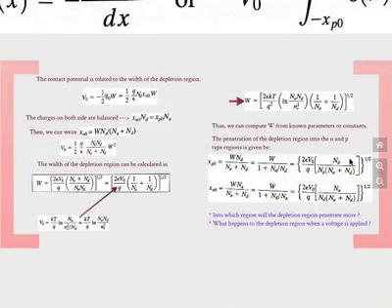So the easiest way, we just saw this, you can plug it in here. If you look at this equation, you know ND, NA, epsilon is the dielectric permittivity, so you know that. Q is the electronic charge. V0 is the only thing you don't know. This is the contact potential. You can easily calculate that from here. V0, of course, is related to the doping on each side.